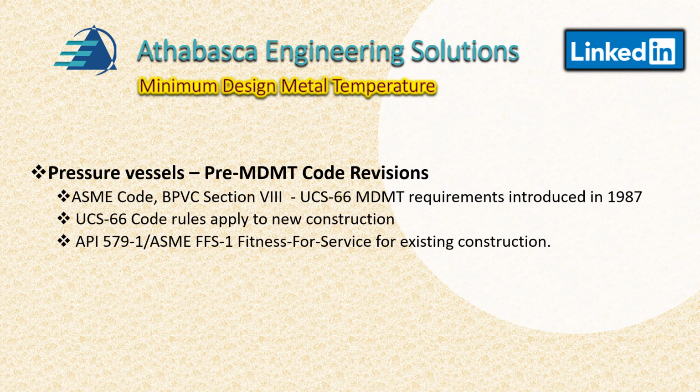So pressure vessels, I want to talk a little bit about that. I call it the pre-MDMT code revisions, because prior to 1987 there was really no UCS-66 available. I think there were perhaps some WRC documents on that topic, but prior to that there were no specific rules.